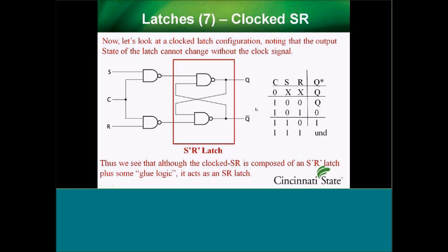Okay, so this is a clocked SR. This is a true sequential logic circuit. It's synchronous. It's timed in with the clock and everything. It still has an undesirable state here, which we're going to address very soon. Matter of fact, next slide.